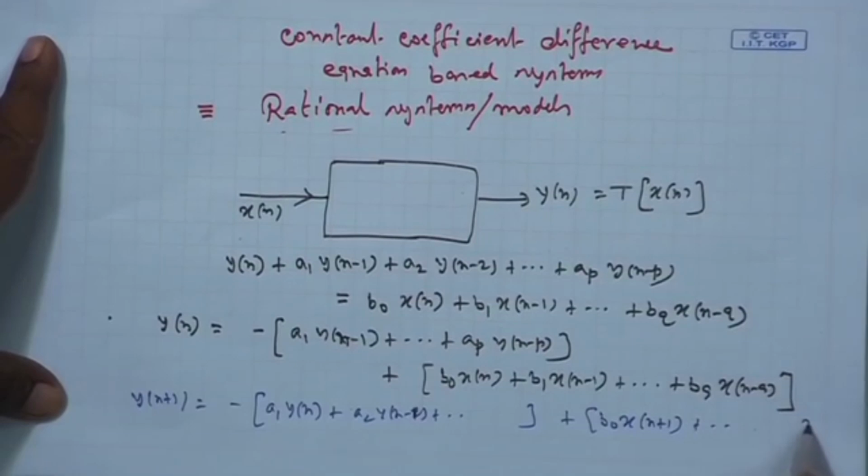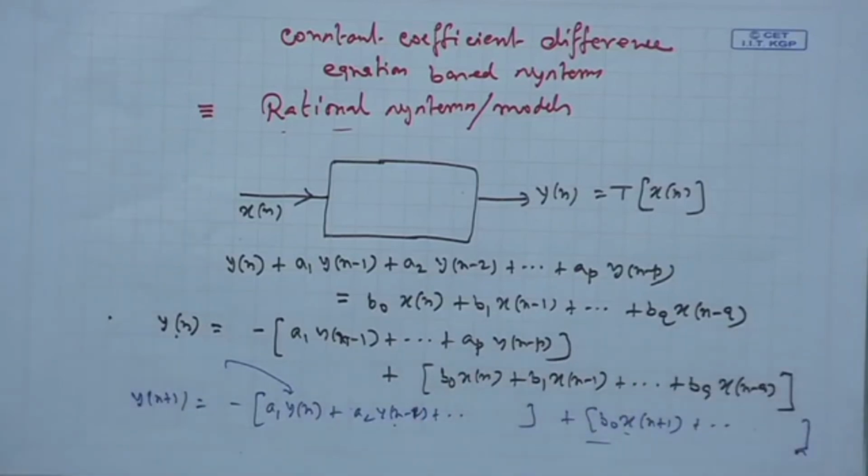Essentially, the y[n] which you computed now, you put back here, and the past output terms are already available. The current input will be x[n+1] and past input terms are available. So, this is not a problem, and you get y[n+1]. Then again at the next index n+2, put it back here, and this way it continues. Okay.